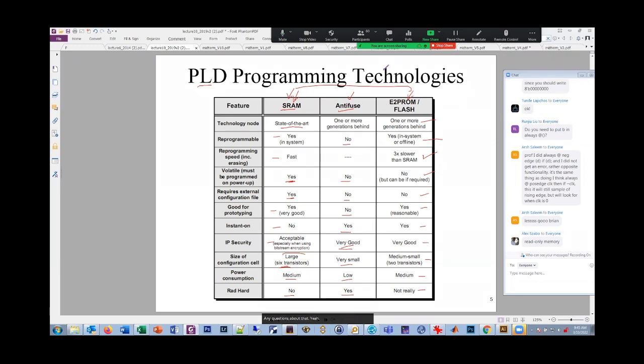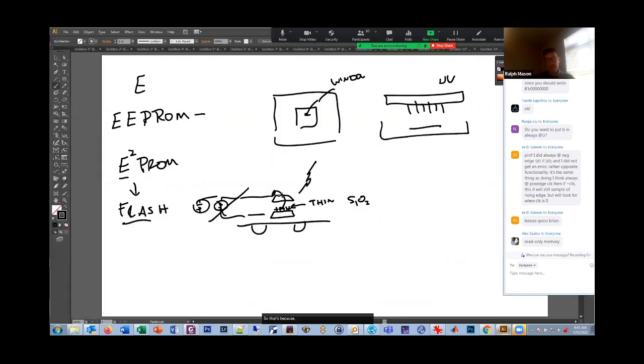Yeah, I'm working with the EEPROM of the Arduino board, and when I was doing research on it, it says that it can only do something on the order of like 50,000 read-write cycles. Yes. So that's because when you apply this large voltage back and forth, eventually it degrades this oxide layer and these transistors. So they have a maximum cycle time.